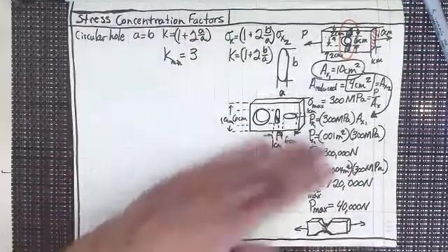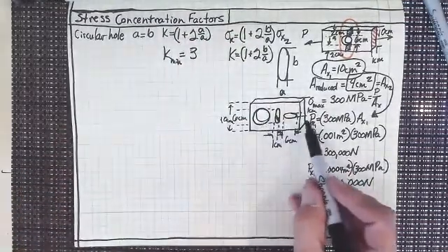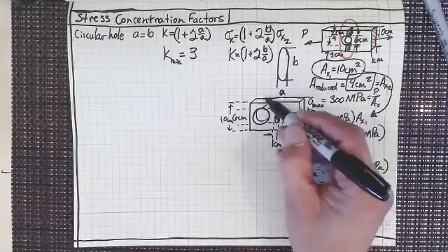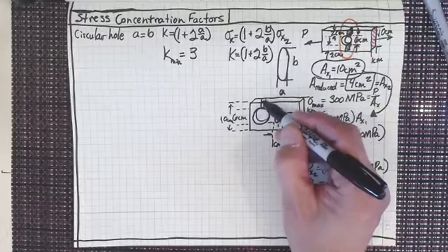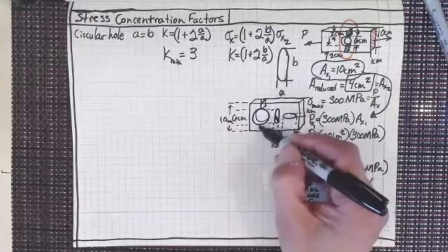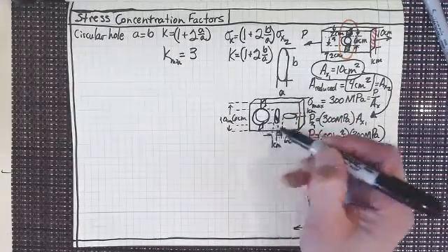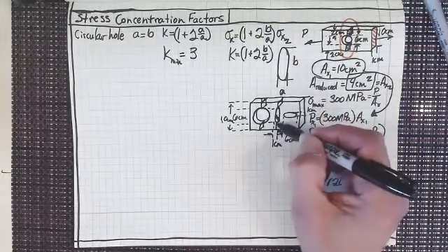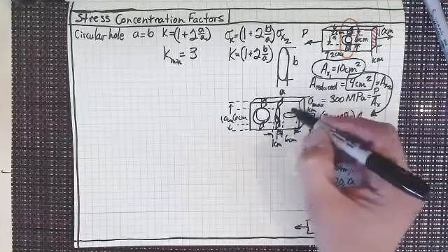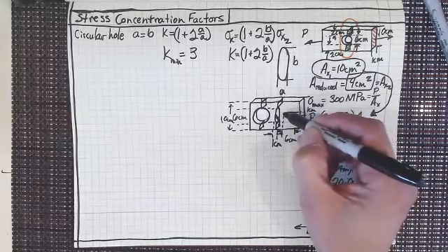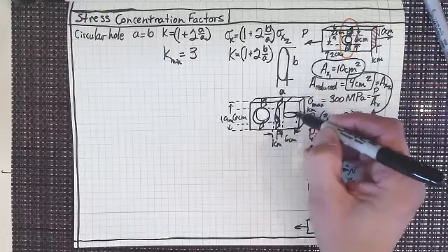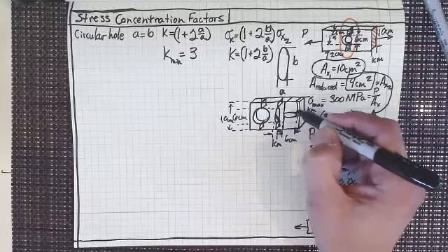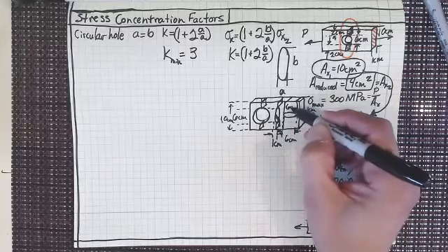All right. So what we want to do is look and see what the actual stresses are going to be. Now, in this one, we've got a reduced cross section there and down here, and we've got the same reduced cross section up here. So these are both going to have the same A sub x2, but not this one, right? This one is going to have a much larger one, because this is 6 centimeters.